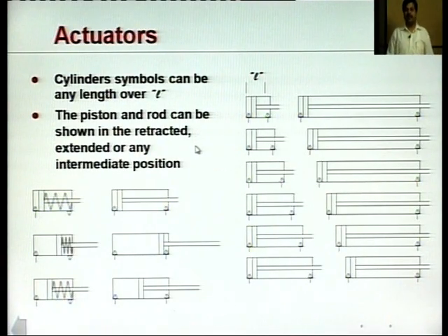The actuators are the main components or the basic muscles which are actually working in that pneumatic circuit. They are the devices to which compressed fluid is provided, and they convert the power of that fluid into the mechanical motion that has to be used in that particular pneumatic circuit. Most commonly we use cylinders, with cylinder and piston arrangements in them, as an actuator in a pneumatic circuit. These cylinders can be single acting cylinders, as can be seen over here, or a double acting cylinder which is shown over here.